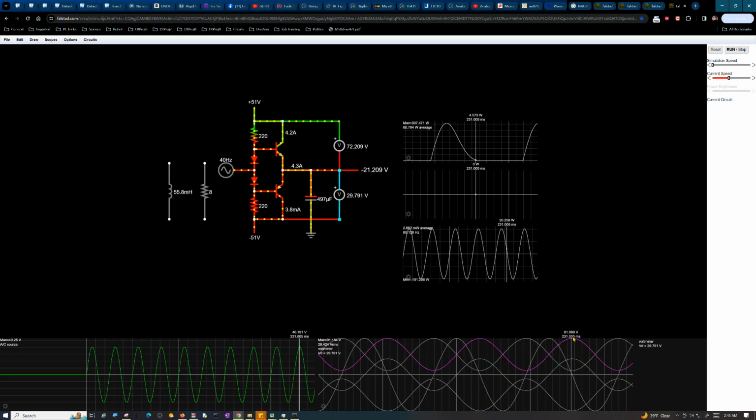So that's when you get the peak voltage across the capacitor, when the transistor is fully on. The purple one is the lower transistor, and the red one is the upper transistor. The upper transistor is fully on. That means the transistor has minimal voltage drop across it at that point, and that means the capacitor, with reference to ground, has charged up to as close to the power rails as it's going to get.